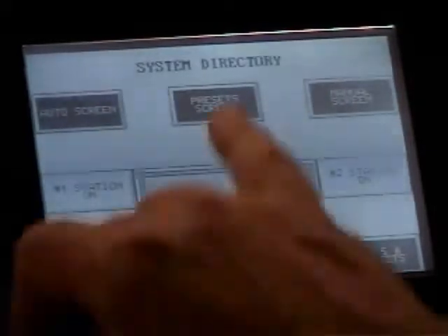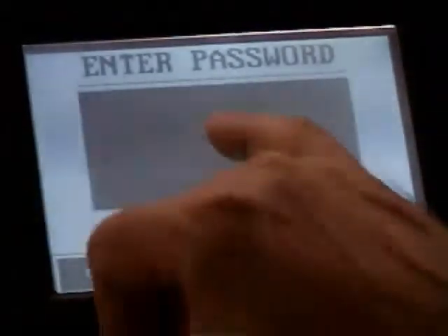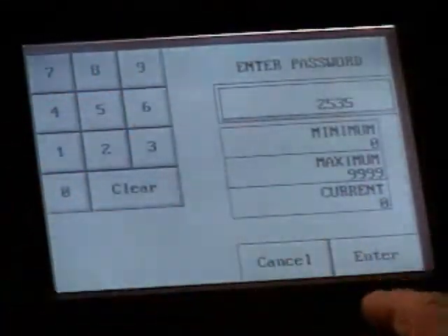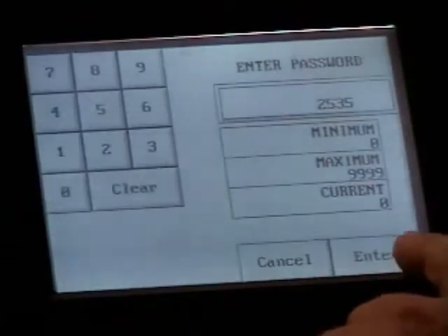Okay, let me go back, show you the presets that we had programmed for this unit, for this flat plate heat exchanger. The first preset, upper left-hand corner, is the charge pressure. It's what the unit will be filled to. Right now that preset is at 400 pounds.